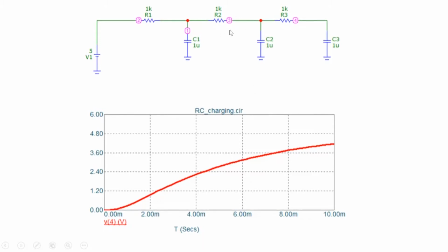It's understandable that this capacitor has to charge, and then this has to charge, before enough voltage builds up to cause a charging of C3. So this is the bit of delay that is there. The point is, as you add more capacitors and more resistors in the circuit, and as the system progresses from first to second and third order and so on, it is still charging. We know a capacitor has to charge to its final value, so that is okay. But the charging becomes more complicated, characterized by several time constants.